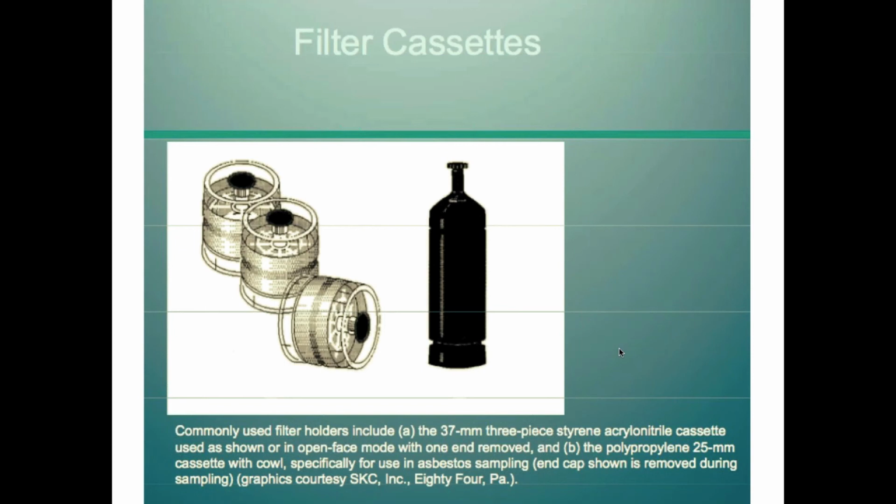Others of these are such that they are matched. There are 2 of them that the laboratory has screened, and they're almost precisely the same weight. You expose one of the filters, the other one is a blank, and you send both back. You don't expose one, you expose the other, and they find the differences in the 2 of them. So there's 2 ways that you might get filters like this from the laboratory. Most of the time, though, you'll just simply get your own and expose them. So I'm going to cut this open, and I think I have at least 2 knives of some kind that you can use.